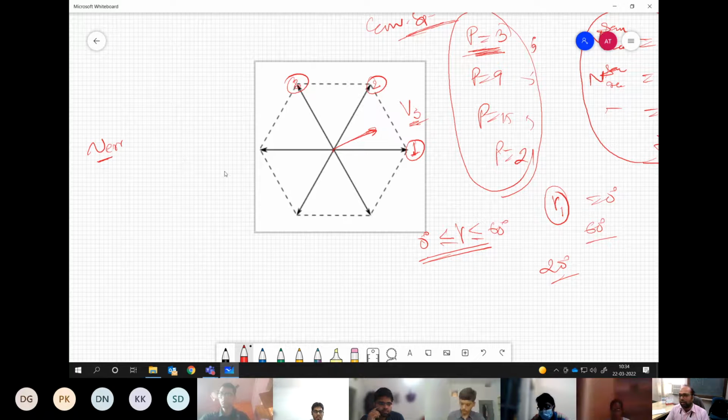Now here the error is not a scalar quantity. It is also a vector quantity. V error is basically what? V applied minus V actual, say Vs. Correct? So if you are realizing this vector using this V1 and V2, this is the kind of error vectors you are applying. V error is basically these two red lines, or maybe I can write in black. These are the error vectors. Whereas if you try to put 3, you will have an error vector which will have so much magnitude.